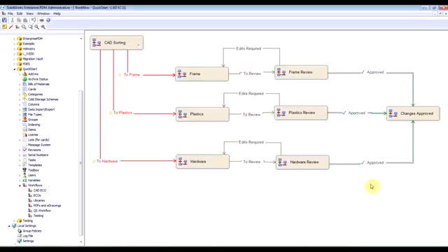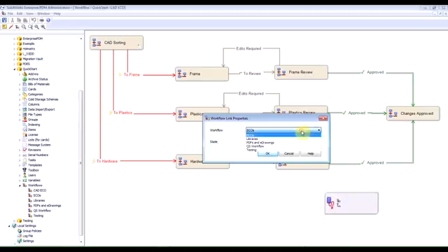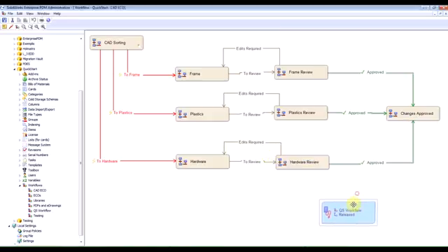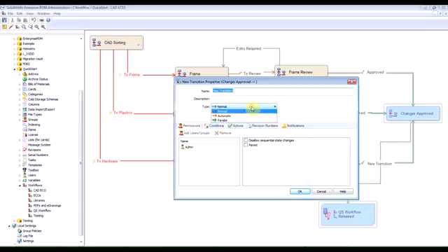But in this case, once a file gets approved, it requires 2 people. The files will go from review to approved. And in this case, I want to not just have files sit back in here. I want the files to get back into the CAD workflow and increment the revision to the next level. So we'll make another workflow link down here. And our workflow for our CAD files is QS workflow. And the state will be in the release state down here. So once files have been approved, we just want to make a transition to go from changes approved to that workflow link. Make it automatic.